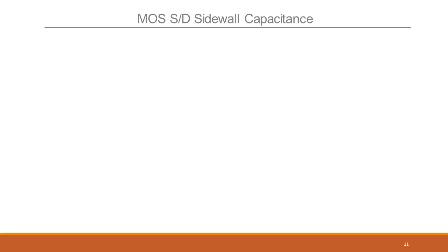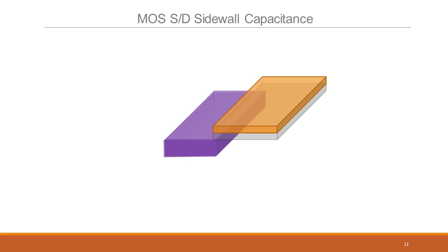Okay, let's now turn our attention to the sidewall capacitance, the two PN junctions that we talked about. They're all reverse biased, so no problem at all. I'm just drawing a cross section of the gate, the oxide, and one of the source and drain, just to show you where we are. It's a geometric problem, because we know how a reverse bias junction capacitance works. It is proportional to 1 by root V, and is proportional to the doping concentrations and other things.